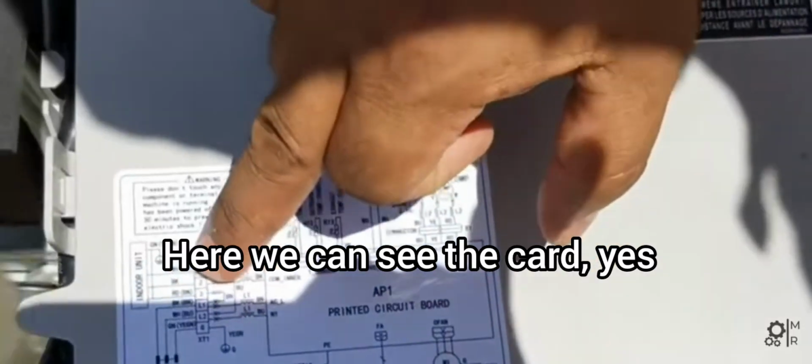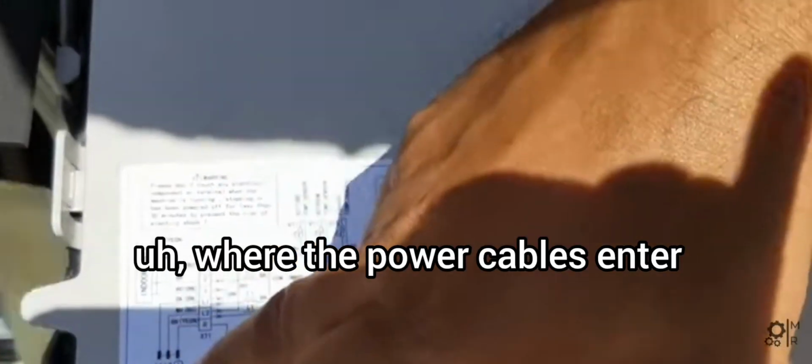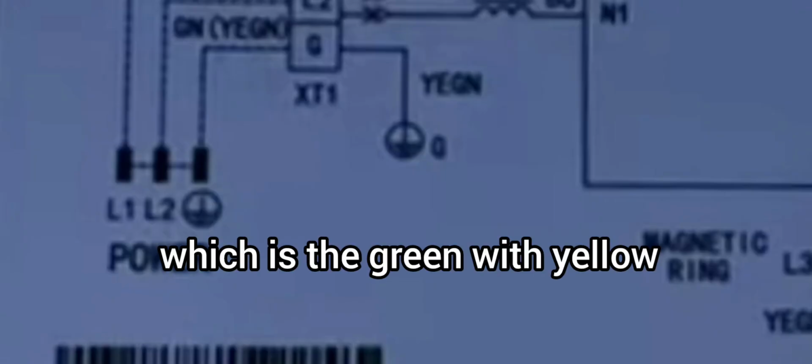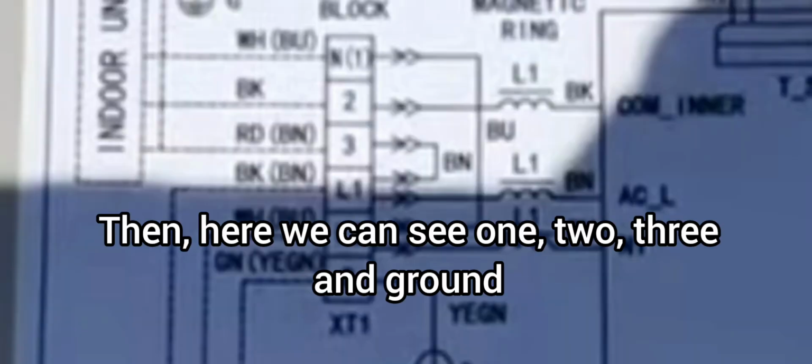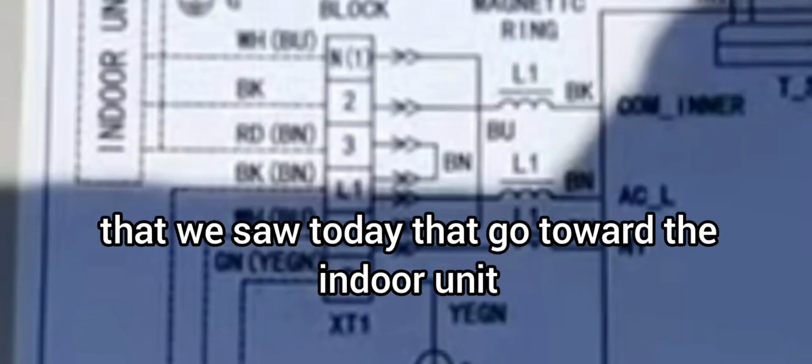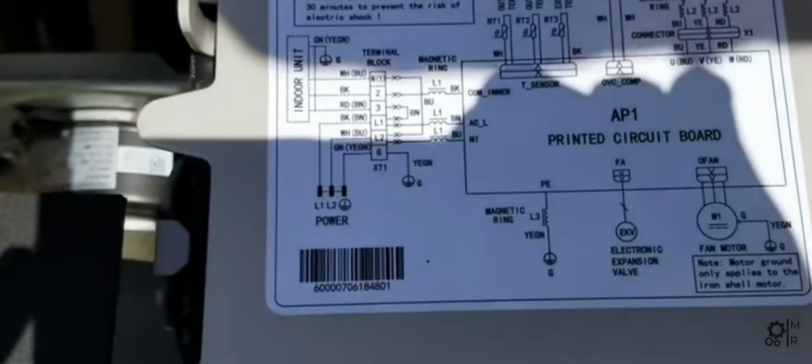Here we can see the card, where the power cables enter, and we do a zoom. And we can see L1, brown, L2, blue, and ground, which is the green with yellow. Then here we can see 1, 2, 3 and ground, which are the cables that we saw today that go toward the indoor unit.